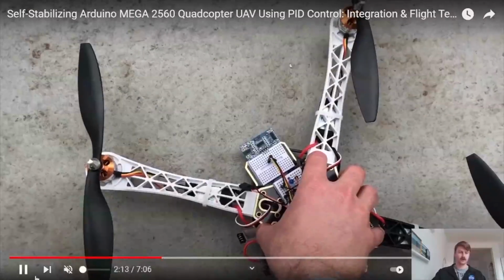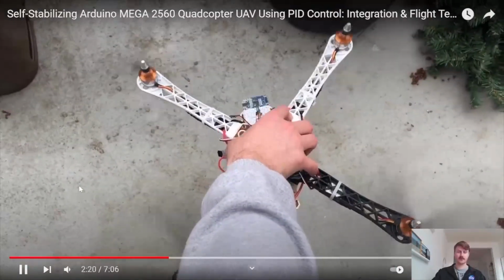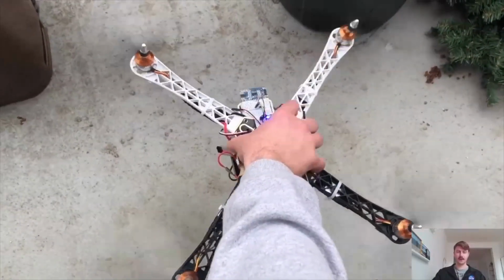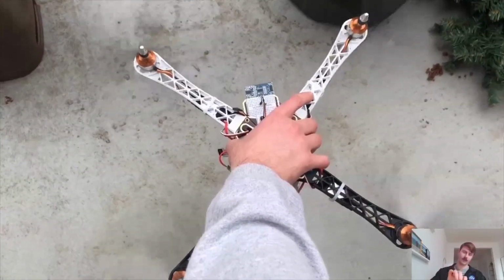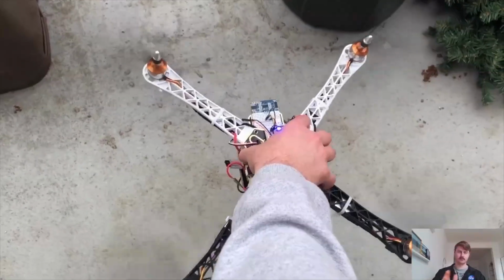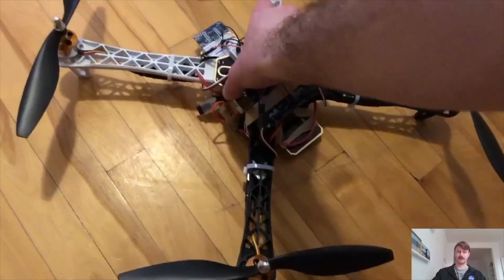So here I'm just going to unmute that a little bit. So here, this was after everything was all integrated, and this was before the tuning of the PID, so just the P gain. And with that, you can hear that it is doing its adjustment. So as I move it, you can hear the propellers trying to compensate for the move or the shift in the body position that I did.